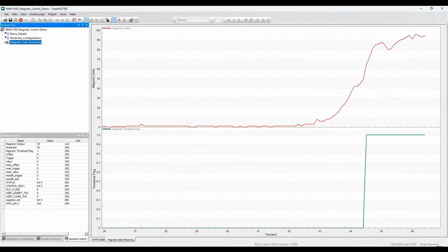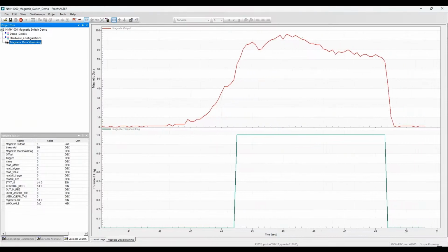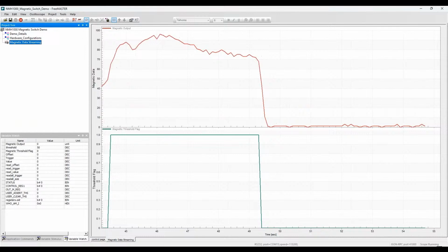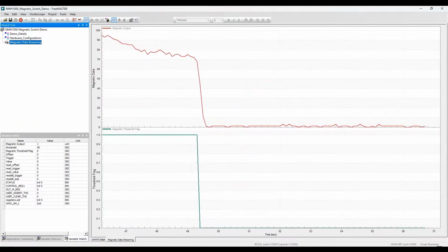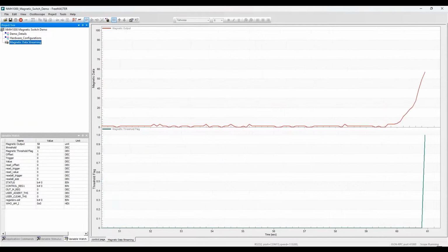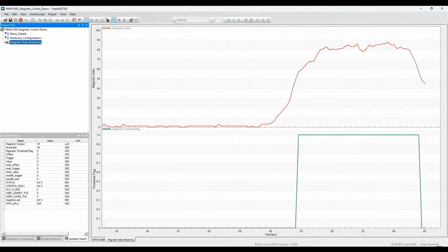And you'll see that the mag wake up is detected. When I remove the magnetic field from the NMH1000, the flag goes back to 0. So this device can be used as an on-off switch based on change in magnetic field, as you can see.